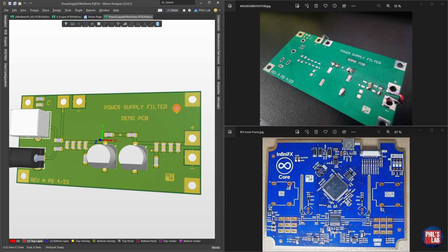To help us do this, we were using function generators and oscilloscopes, as well as this power supply filter demo PCB, which will be upcoming in various other videos as well. Here we can place different capacitors, resistors, series and parallel elements, and then examine their properties. The PCB you can see in the top right, which has already been messed with quite a bit, that's why it looks a bit rough, is what we'll be looking at and using to inspect RC high-pass filters in a practical sense.